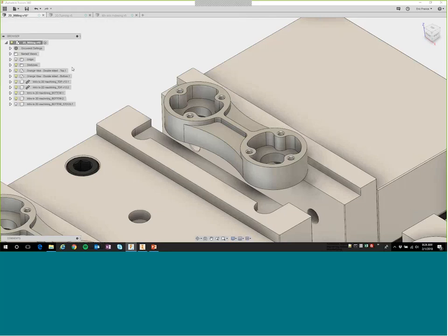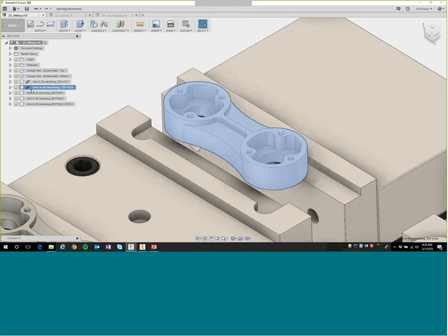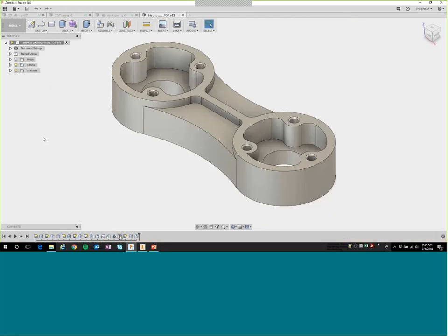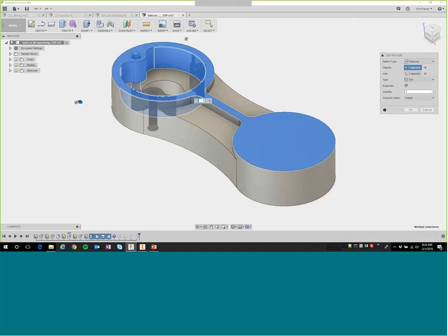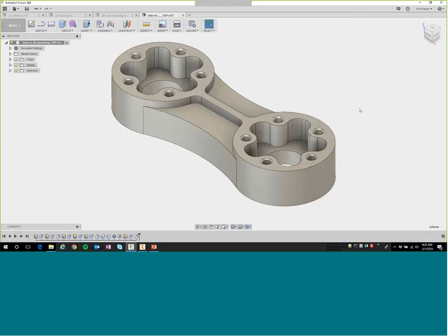So let's switch over to model, and we can see we've got this top that I want to make the change to. I'm going to open that up because it's actually a linked model in Fusion 360. In here we've got access to the feature tree, so I can edit that feature. A simple modeling change, going from 3 to 5. From a modeling standpoint that's pretty easy to do, but from a programming standpoint, we've now made some significant changes to the overall code that needs to drive this. So I'm going to save that out.